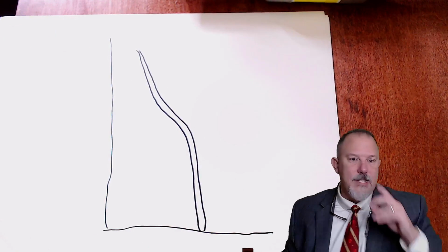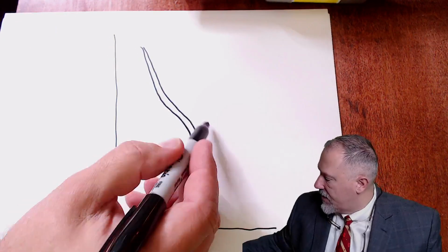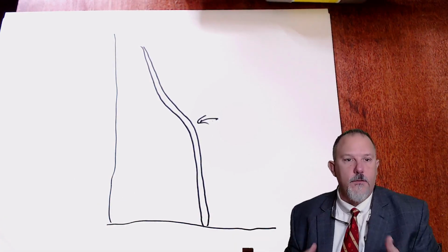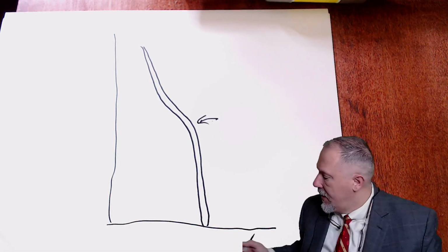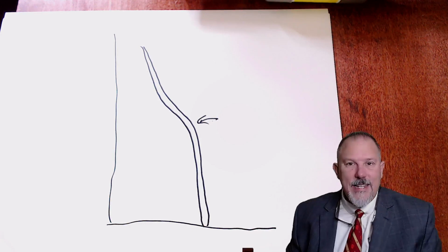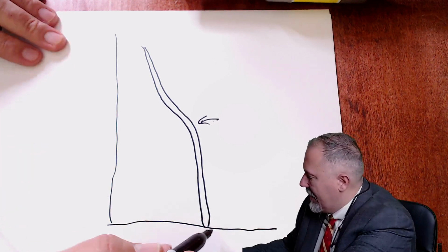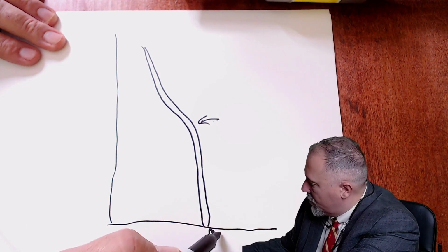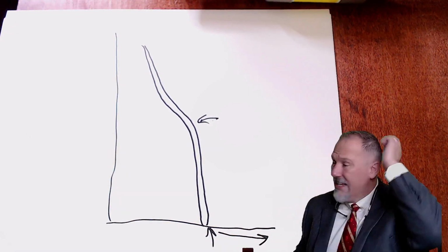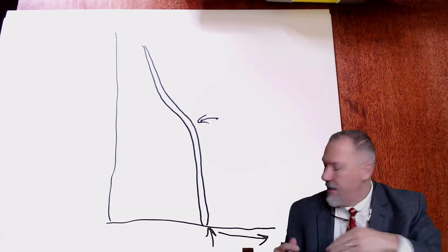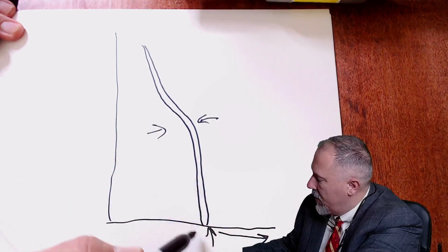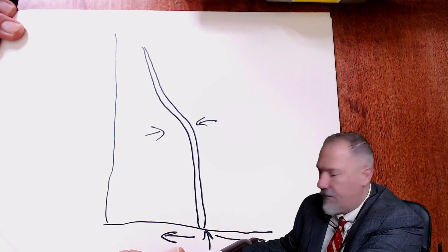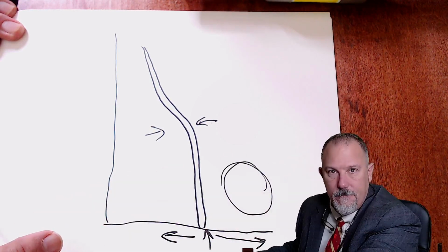So there's your time delay type of fuse. You'll notice I have a little knee up here, and that helps a motor starting curve or transformer inrush, things like that. Now, when we say current limitation, it doesn't happen until your current gets higher than that number. So over here is your current limiting region. When I say current limiting, I'm not talking about anything on that side of the trip curve. I'm only talking about the performance of this device in that area.